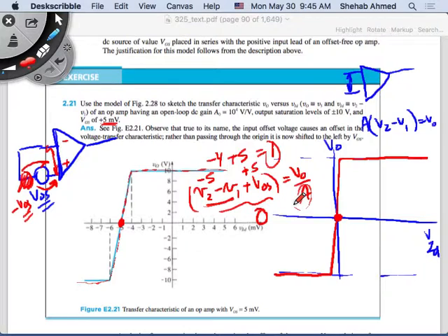Now, after you said that, let's say it's minus 4 plus 5 equal to 1. Also, it's going to be 0 at minus 5, since minus 5 plus 5 is 0, so that's where the zero crossing is. So if you're designing a comparator and your op-amp has an offset voltage, this is going to ruin your comparator, if you're comparing signals that are a few millivolts, right?